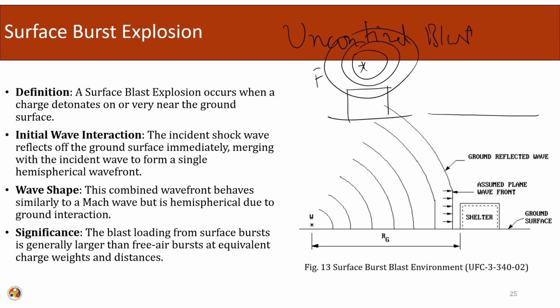In the air blast, the blast occurs above the ground, and its signature is a mixture of the incident waves and the reflected waves. There a Mach front is made, and using the available design charts we can calculate the different quantities: the overpressure, the reflected pressure, the incident pressure, impulse, positive phase duration, negative phase duration and all the required quantities.